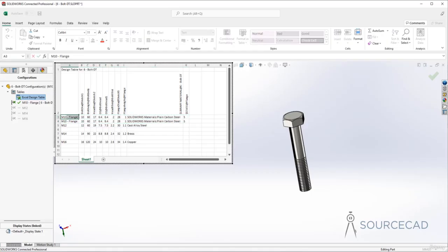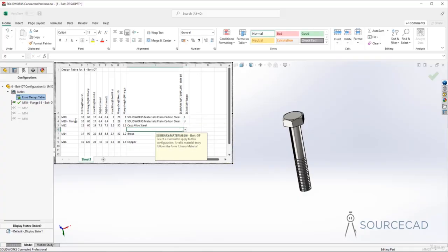But then we have the suppressed one. So here I'll hide the flange option. Flange will show for unsuppressed, and now I'm going to change this to U. So for unsuppressed, the flange will show, and in this one, flange won't show. So for that, I'll select suppressed. In a similar way, I'll give new names for this one.